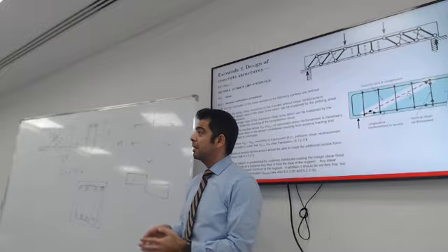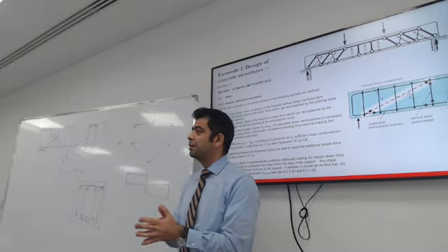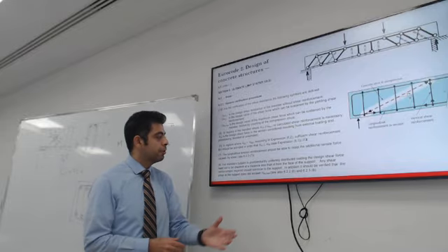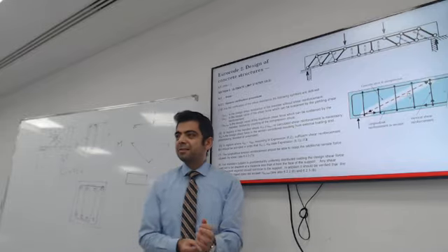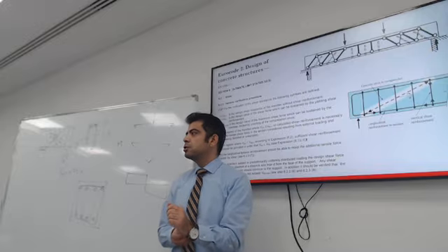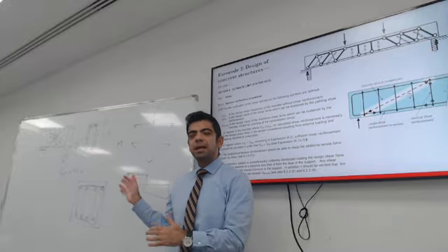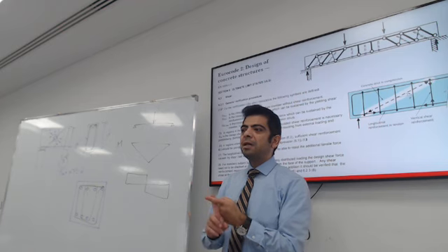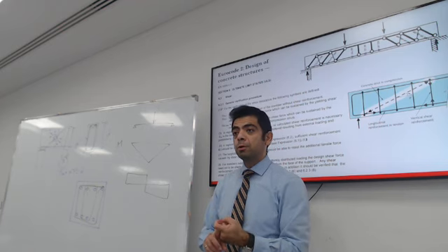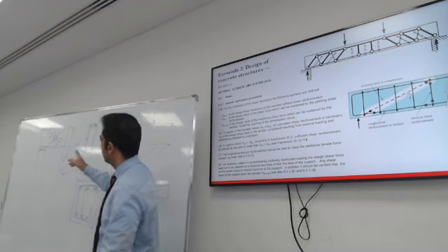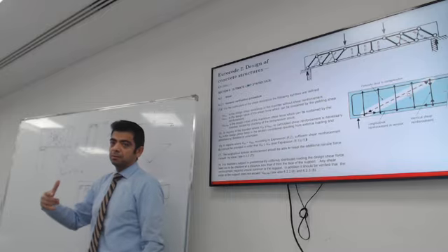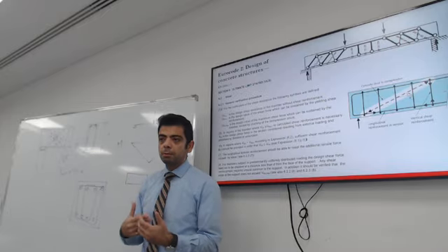Think of it as the guideline to design concrete structures. It might seem like a lot of information, but in essence, there are a few things that I need you to understand, and I've said it mostly already. There is such a thing as minimum reinforcement, minimum shear reinforcement. Do not leave your beam without stirrups. You can use minimum reinforcement.